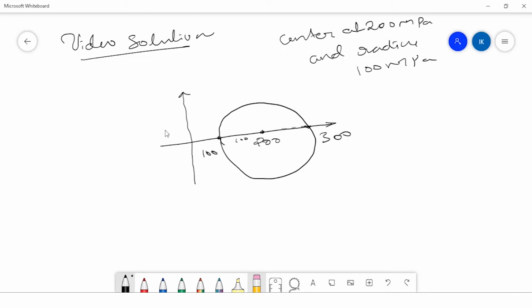Now what we have to find is the plane at which the normal stress is 260 MPa. 260 MPa means the point will be around here, between 200 and 300, close to this point. And we have to find the magnitude of the shear stress. The shear stress can be this line or this line, but this line is negative, and what we need is the magnitude.